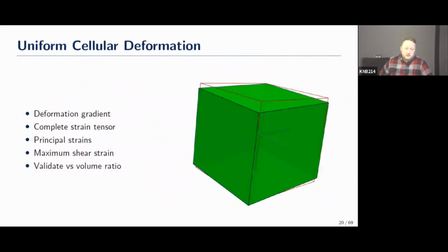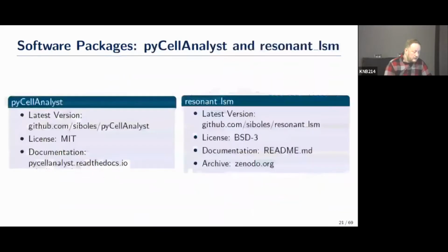And when we solve that optimization problem, we get what's called the deformation gradient, which is a very, very important quantity in continuum mechanics. Basically, we can describe any sort of strain measure, anything that you learn in your undergrad engineering courses is a function of F. Once you have F, you essentially have it all. And so for the particular cells I showed you, we can visualize that deformation gradient as going from the outline box in red to the green deformed box. So you see there's shears and compression strains occurring on that particular cell.